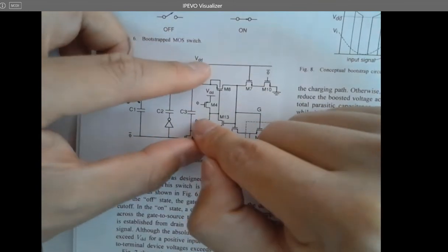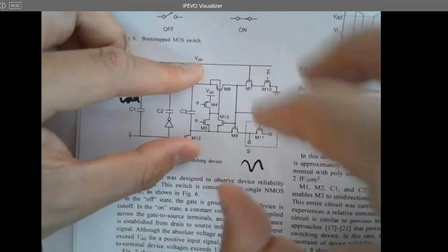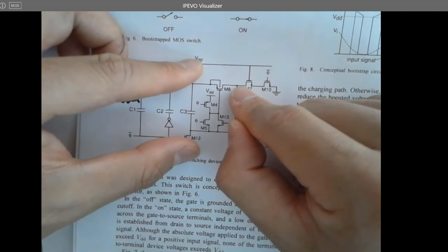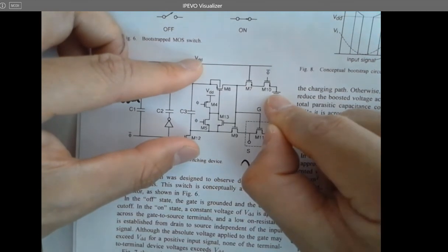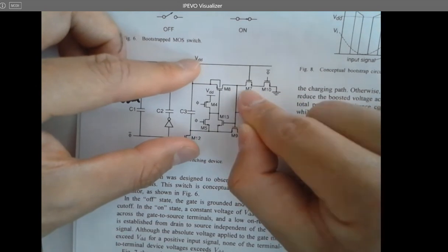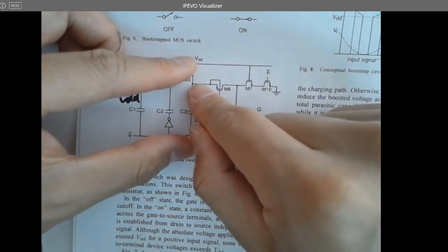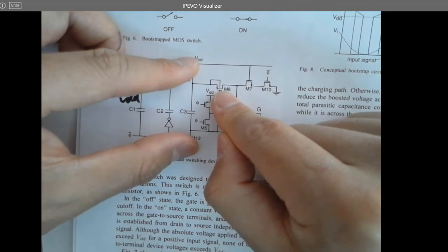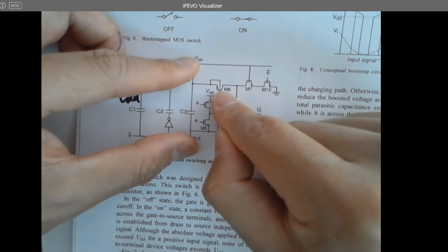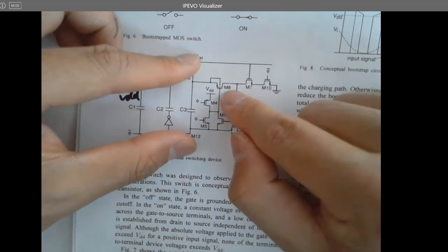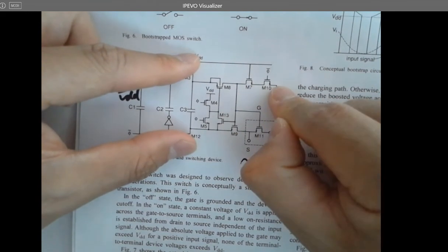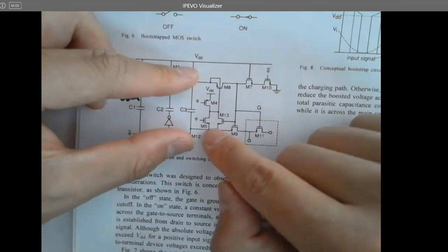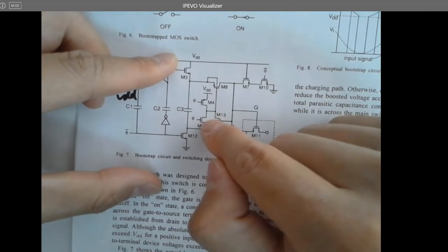So what's happening is when you are charging up, C3 is preparing for something, right? So it's charging up C3. This point is actually being reset by ground. So you are worrying, hey, if I'm resetting this point and I'm boosting this voltage, am I passing VDD to ground by this transistor? Is this being turned off or turned on? Let's take a look. So whenever I'm resetting this point by the ground, and the same cycle, I'm turning this to on and charging up this capacitor to VDD, you see this inverter is actually controlling this point.